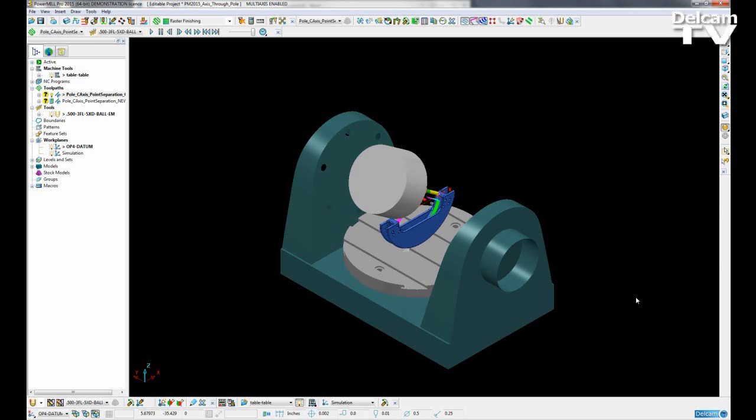What this looks like is as the machine approaches the vertical, the table will rotate 180 degrees while the machine tool dwells in the same point. This can leave marks on the machine, and it also increases machining time. One solution to fix this is to avoid going through the pole at all costs. The option we can use is to redistribute points when the maximum separation angle is used in the settings.